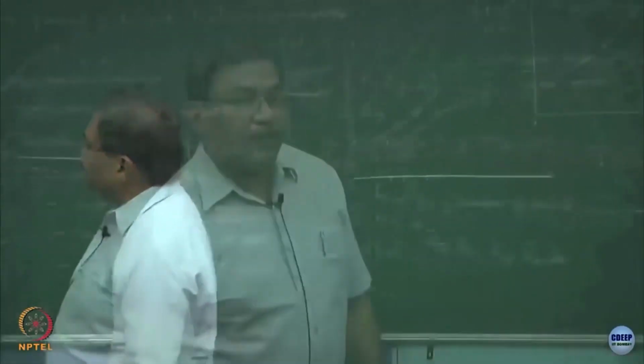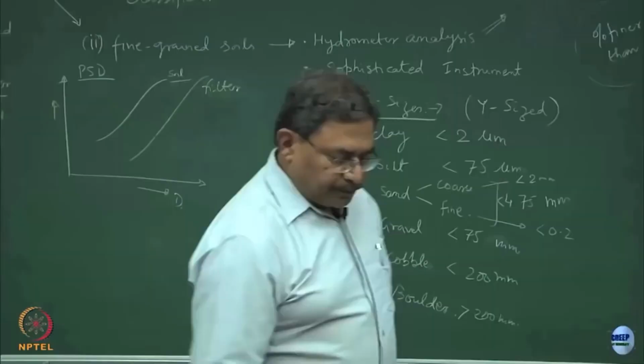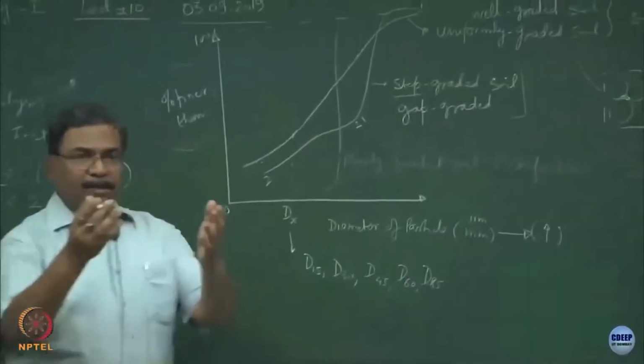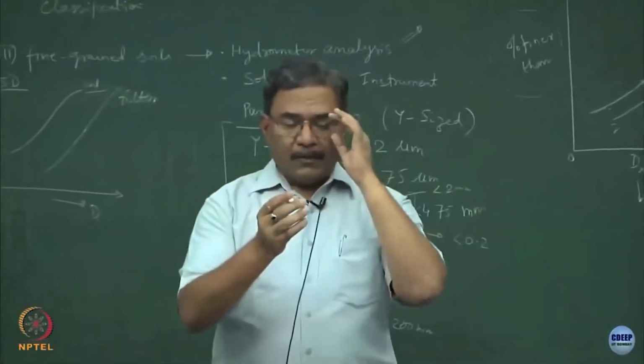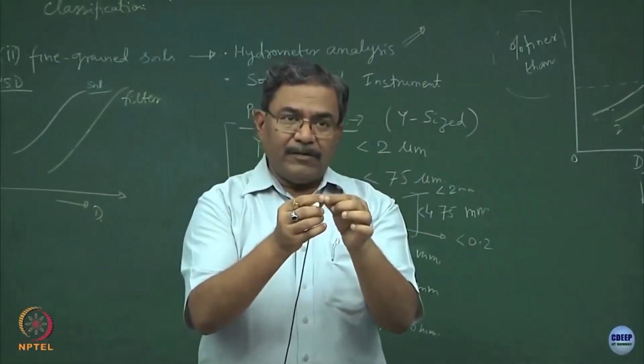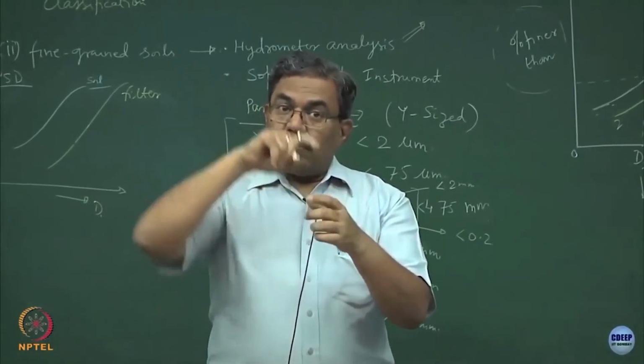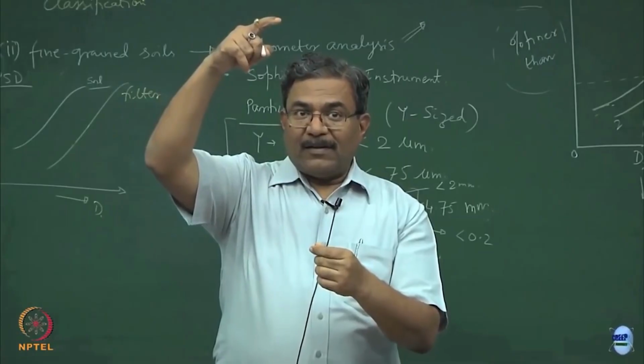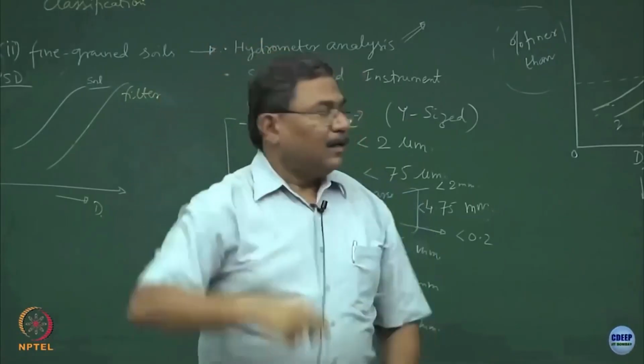Is this part clear? Diameter of the particle increases, the percentage of its fineness should decrease, right? Very good question. Remember, this graph has been obtained by sieving. You must have done sieve analysis in the lab. So, you must have seen the apertures on the sieve, clear. So, is the topmost sieve a big aperture or a small aperture sieve? Bigger. How would you read this?